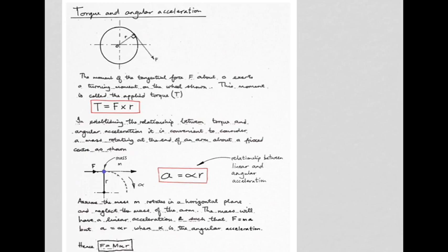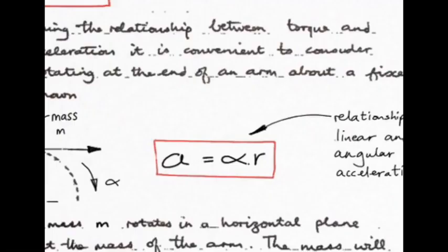Second moment of area, which we've just done, had units of meters to the fourth, and we were basically taking an area and multiplying it by the square of the distance from some axis. Here the similarity is we are taking a quantity and multiplying it by the square of the distance from an axis. However, the quantity is now mass, not area.